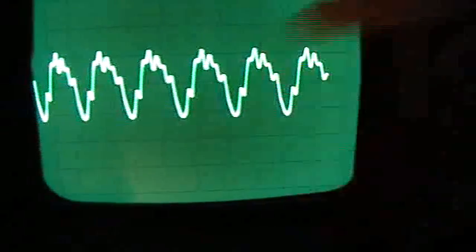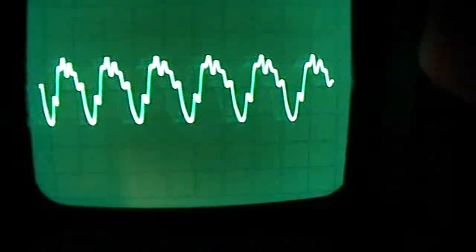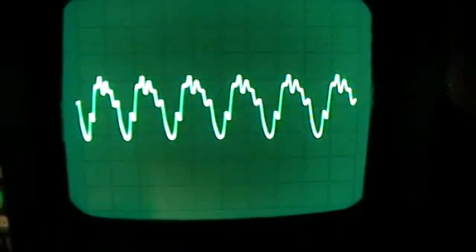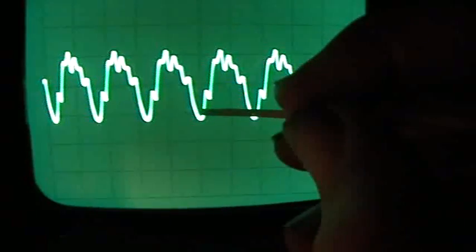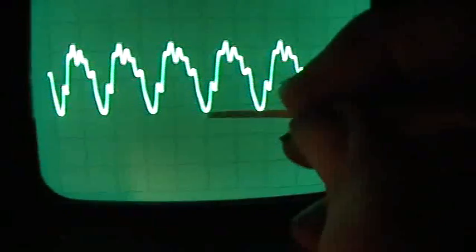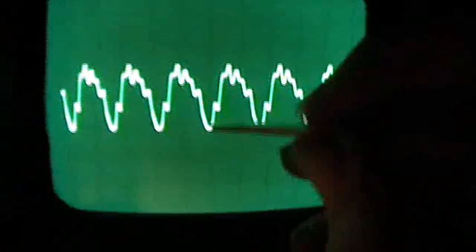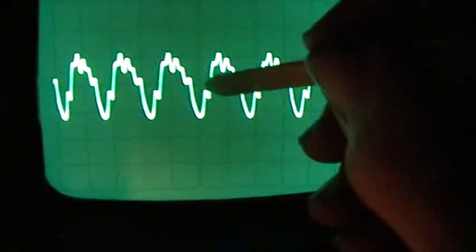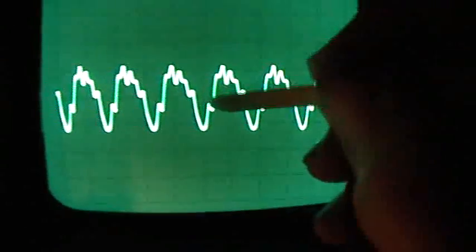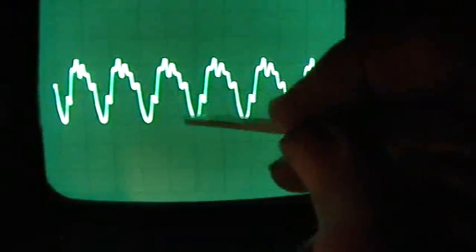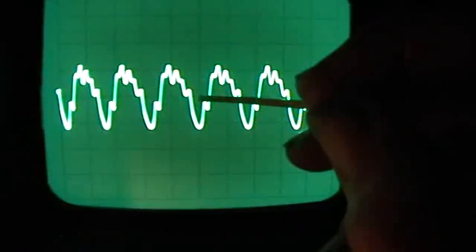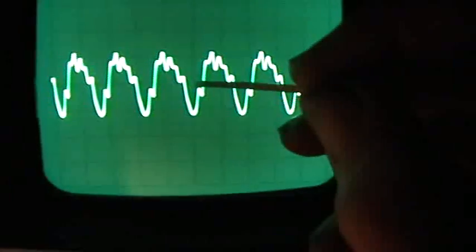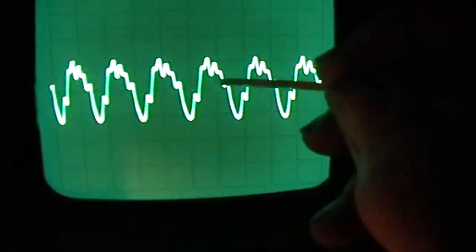Okay, now the bottom peak, same thing. We'll move the bottom peak over until we're right on a graticule marker, and we'll count down 1 major division and 1 minor division. So that's 0.6 of a volt, right? So we have the same peak current going in one direction in this AC oscillation as we have going in the other direction.